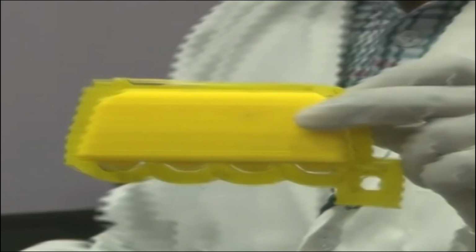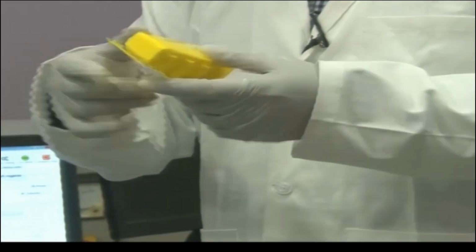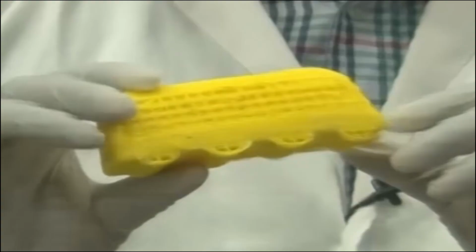This extra material is brim. Also we have more extra material here. Those are supports that we will show you, how when we remove them, we can remove brim by hand very easily, manually, and we can get the finished final product. If the CAD model is flat, it's okay. If it is not flat, if it has some inclination, as I said, what would happen? How would the machine take care of the printing? It would provide some support.